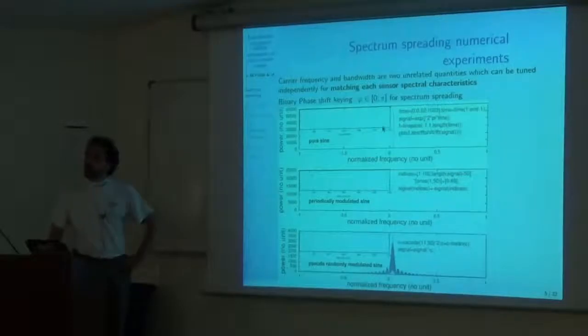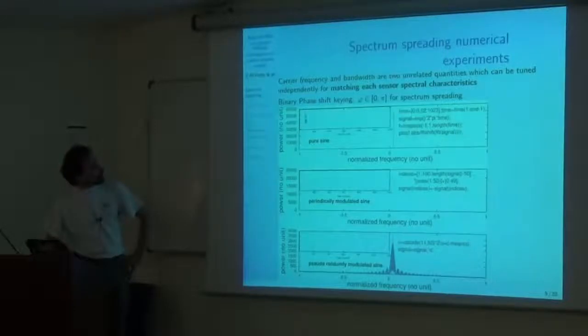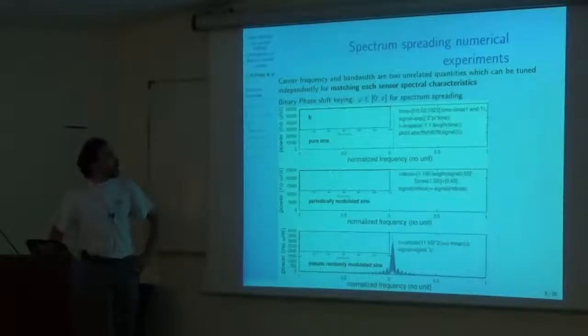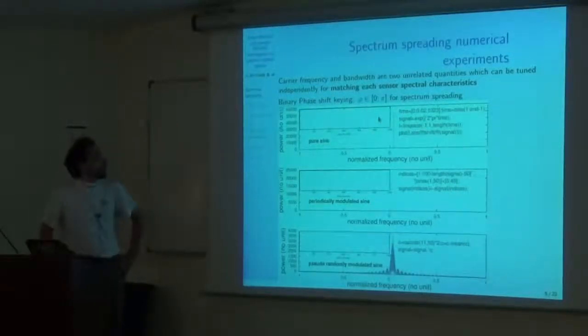So the first thing I'm doing is I have a continuous wave. You might be able to see here on the slide, I'm sending a continuous wave, just a CW carrier, and the Fourier transform of this continuous wave carrier is just a sharp delta Dirac. It's a sharp peak in the frequency domain, offset from 0 hertz by the frequency of this signal. Now, a continuous wave has no timing characteristics. You just cannot make any difference between this sine wave period and this other sine wave period. They're all the same. So how can I put some timing information in here?